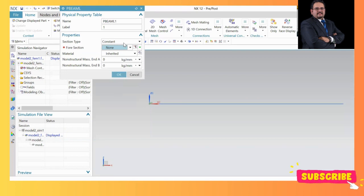If you are analyzing beams, then your element should support the beam, right? Because a beam should facilitate the stresses and the bending, but it should not have any torsional capability. So when you specify this, you are saying that the element you are using supports only beam, right?